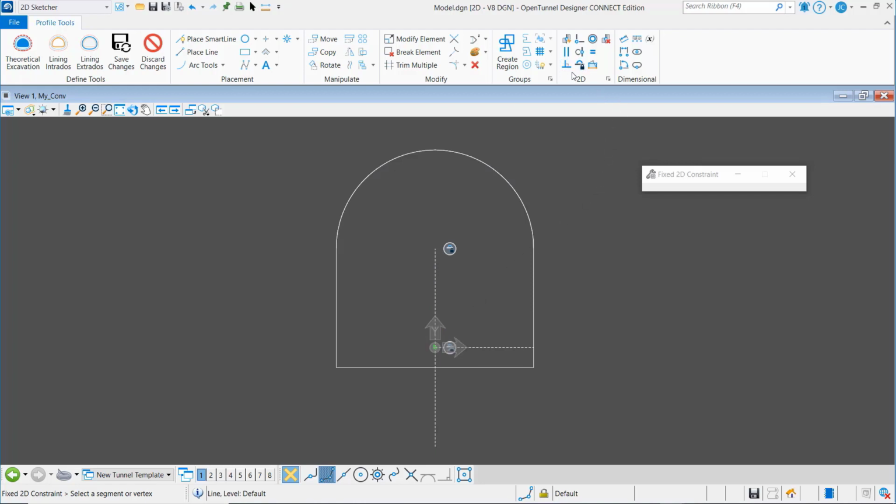That means that we fix both ends of the first vertical line, which will be our vertical reference. Then we define that the origin of the horizontal line is coincident with the vertical line, and we have 90 degrees, so perpendicularity between the vertical and the horizontal line. So these are our references for the different elements.